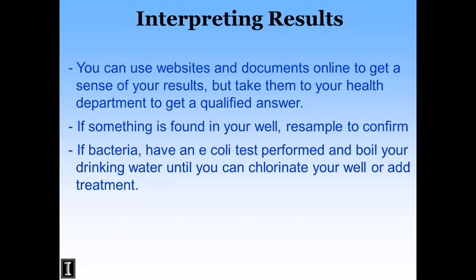So if you've sampled for coliform bacteria and it's positive, then you should have an E. coli test done, and you should boil your water until you can either chlorinate your well or the test comes back and shows that there's no risk. If you have E. coli, that's the bacteria from human and animal waste, then it's a serious health risk, and so it's nothing to take chances with.